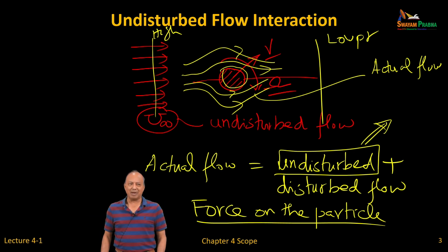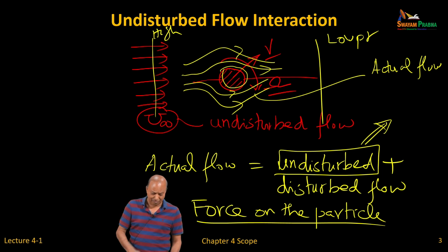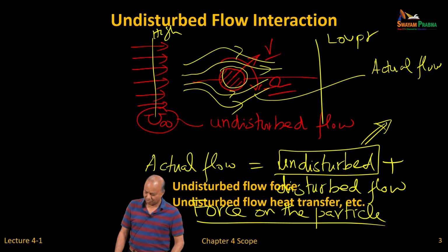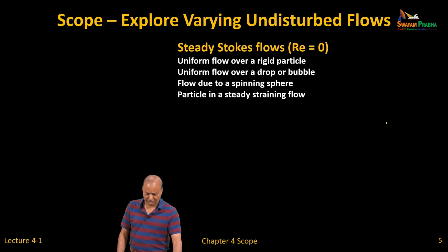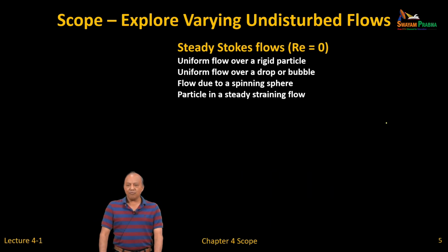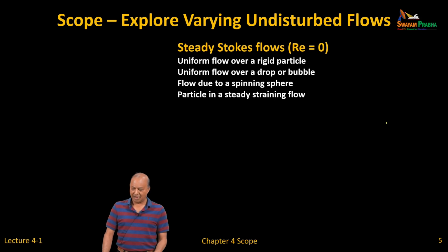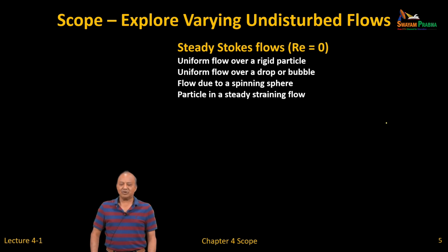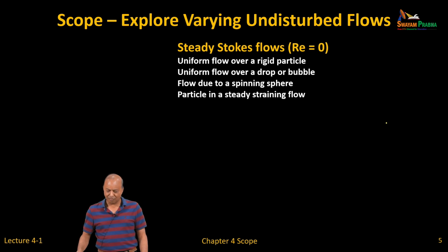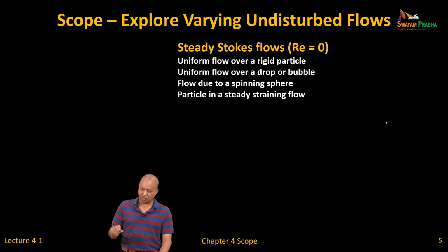You have all probably heard of the Maxey-Riley equation, BBO equation, etc. And I'm going to say a few things. I won't derive this. In the book we have the derivation of those things, but we are going to talk about what it means. So with that knowledge of what undisturbed flow is and the force created by this undisturbed flow, most of our interest is in what happens when the flow gets disturbed, when the flow has to go around the particle.